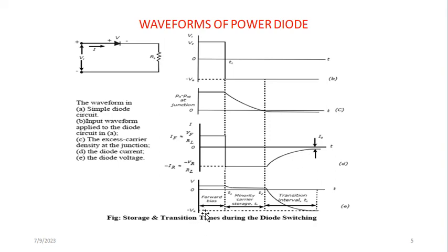And this is the waveform of the voltage. When the input is high, the voltage is high also. When the input suddenly drops to low, the voltage reduces. It is positive, but it will reduce because of the residual charge carriers I talked about. After crossing the zero line, the voltage will start decreasing until it reaches the maximum negative, just like the waveform here, and it will continue like that.